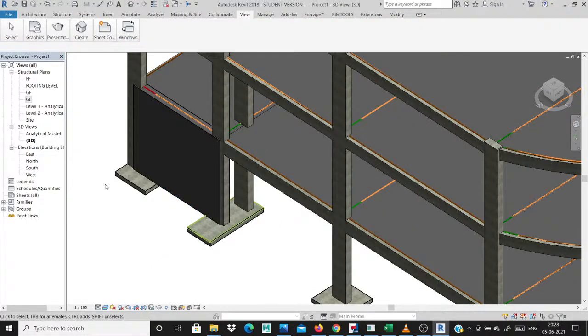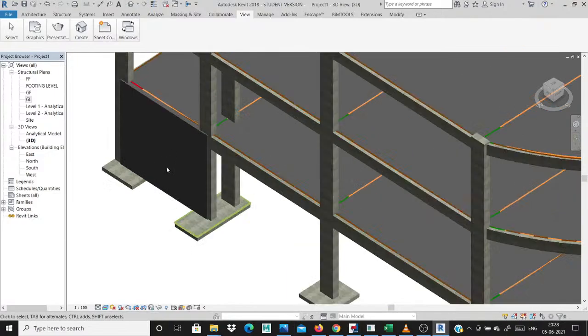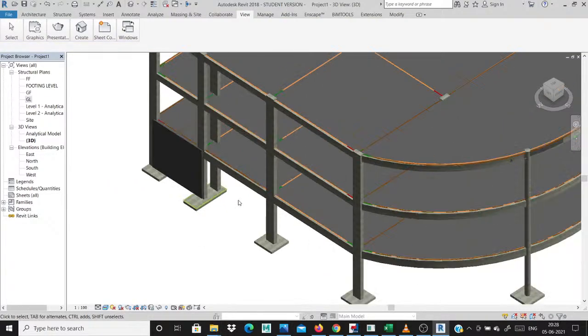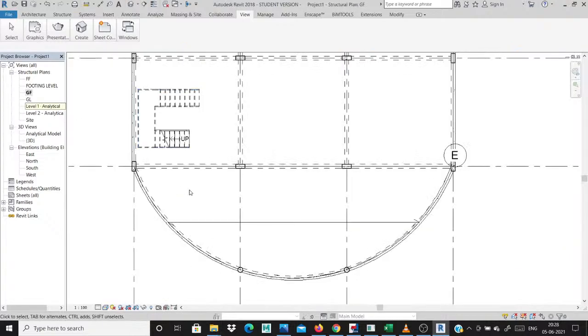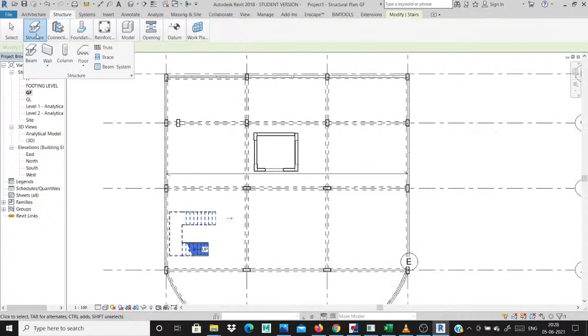The shear wall will be the next category. Then see, automatically my ground floor is fully adapted for my shear wall also. Simply click this shear wall, then it will be created automatically. So, okay, in this ground floor I need a first floor for normal walls. How to create the first floor normal walls?